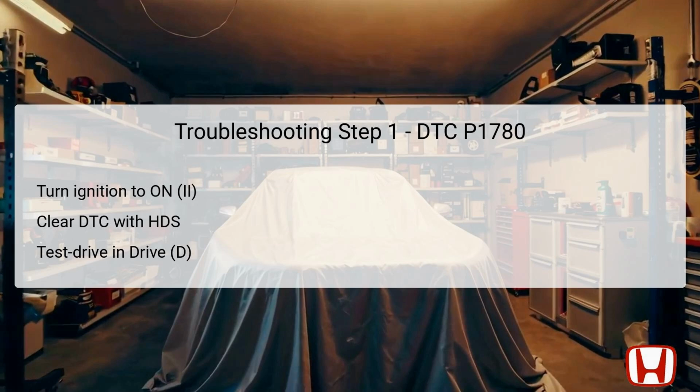After clearing the DTC, conduct a test drive with the shift lever positioned in drive, D. During this drive, allow the transmission to shift through all 5 gears to ensure it operates normally. This step is crucial as it verifies whether the issue persists and is essential for identifying if any other diagnostic trouble codes are generated during the drive. The feedback from the HDS after this drive helps guide the next steps in troubleshooting.